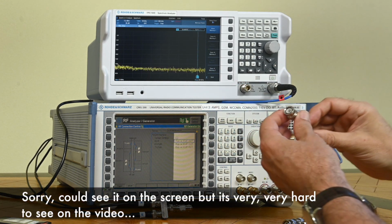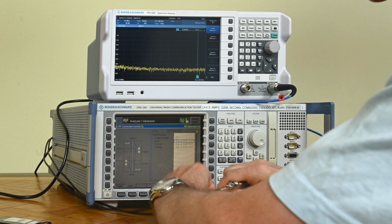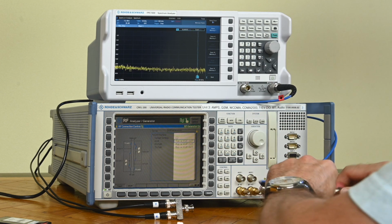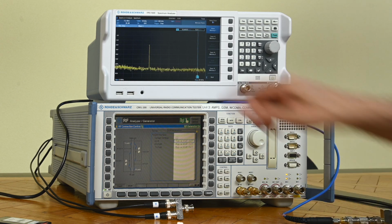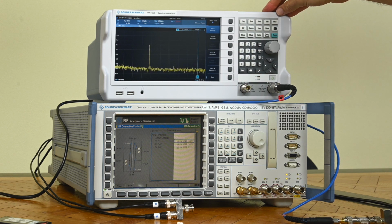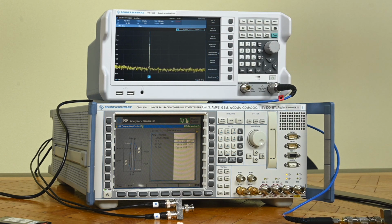So let's see what's happening on the receive path. Now we also get to see an IF signal on the receive path. It's a different frequency than we had on the transmit path. This one is actually 10.7 megahertz right now.